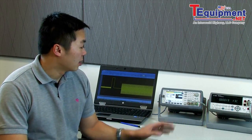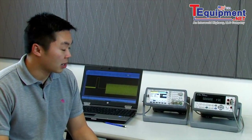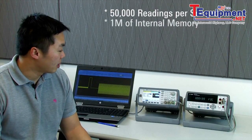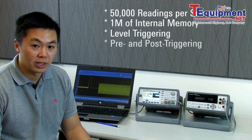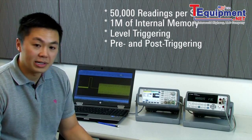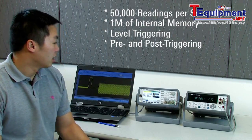I'm a test engineer at Agilent Technologies, and in our video today, I'm going to show you how to digitize using our 34411 DMM. The 34411 has a few additional features that are not available in our other DMMs. It's able to do 50,000 readings per second, has 1 meg of internal memory. It can do level triggering as well as pre and post triggering. So in our video today, we're going to show you a bunch of those features.